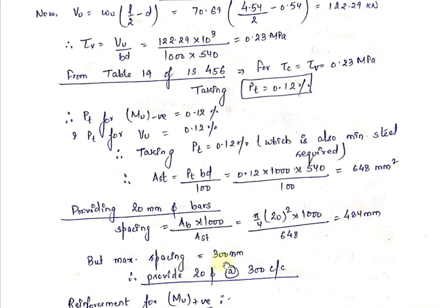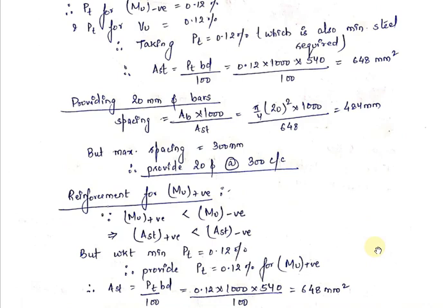But the maximum spacing is 300 mm, which I already told you. So therefore, provide 20 dia at the rate 300 center to center.